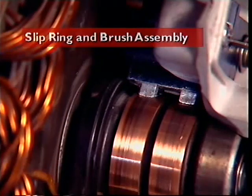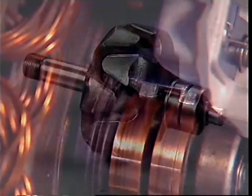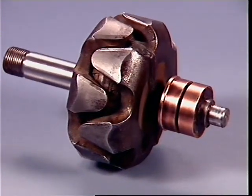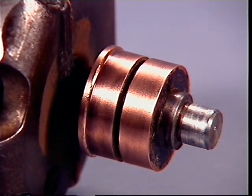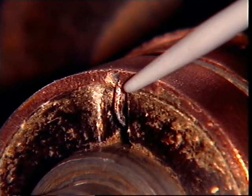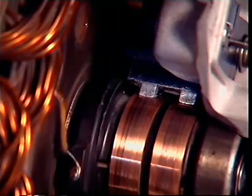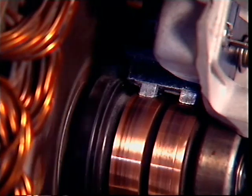This section examines the slip ring and brush assembly. Slip rings are normally copper bands molded onto an insulating material, then pressed on the steel shaft of the rotor. Each end of the rotor winding is connected to one of the copper bands, so that as the rotor rotates, the brushes can make a connection with each end of the winding.